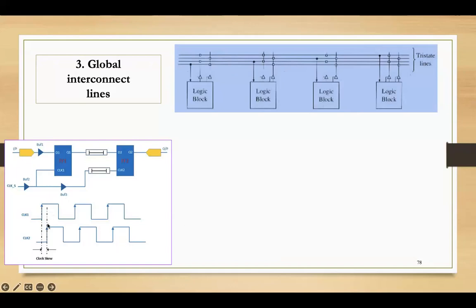Here I've put up a small waveform where you can understand the concept of skew. Let us say clock 1 rises from this point, maintains that level, and then comes down. We expect the other clock to do the same at the same time.